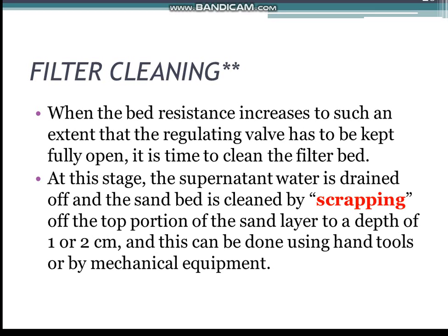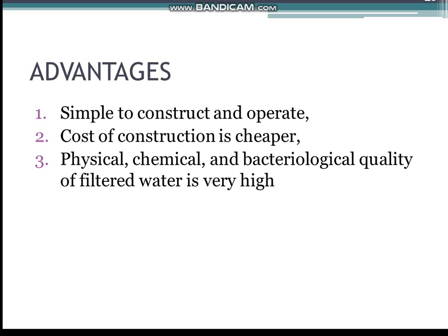Filter cleaning. Normally, the filter may run for weeks or even months without cleaning. When the bed resistance increases to such an extent that the regulating valve has to be kept fully open, it is time to clean the filter bed, since any further increase in resistance is bound to reduce the filtration rate. At this stage, the supernatant water is drained off and the sand bed is cleaned by scraping off the top portion of the sand layer to a depth of 1 or 2 centimeters. This operation may be carried out by unskilled laborers using hand tools or by mechanical equipment.